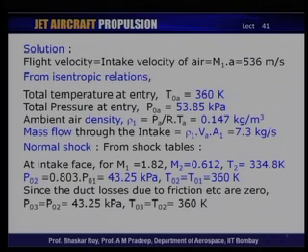P02 across the normal shock would be 0.803 times P01. So, that would be 43.25 kilopascals, and T02 correspondingly would remain same as T01. There is no change in total temperature across the shock, and that remains 360 K.